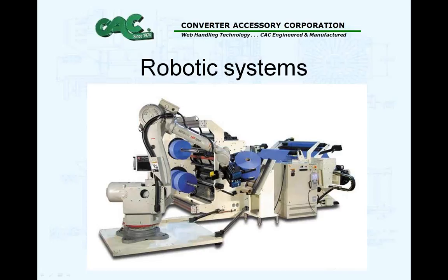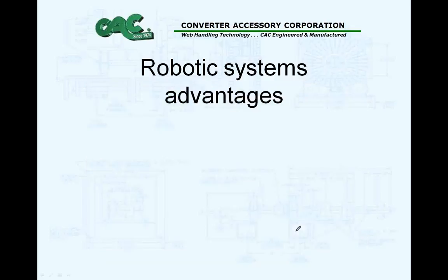The articulating arm is all robotic in nature, and you're grabbing the rolls from the outside with clamps, and the arm literally slides the rolls off the rewind side of a slitter, and then will place them onto a skid or wherever you want to put them into a packaging, however your shipping department accepts them, or your storage department.